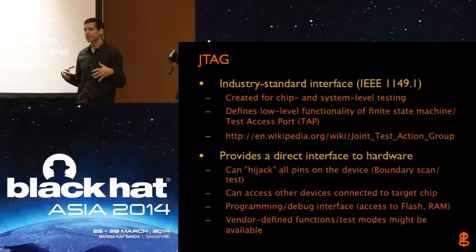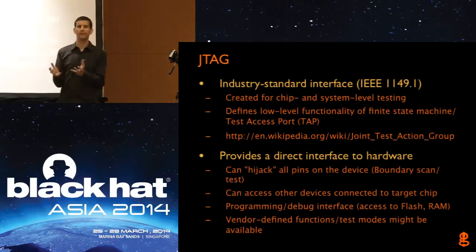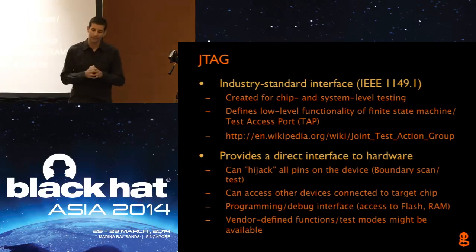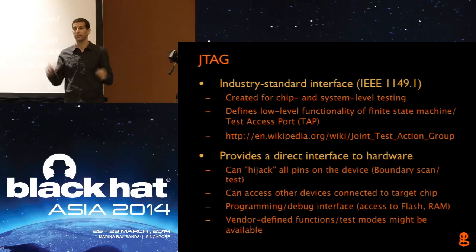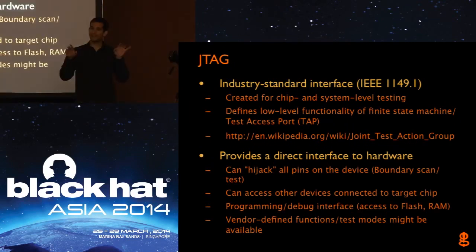Some vendors actually create additional vendor-specific functionality that can be communicated and controlled through JTAG. So it's become this universal interface when it really started as just a very low-level, specific interface to test the connections of pins on a circuit board. What's really cool about JTAG is you can actually hijack all of the pins on a device through something called a boundary scan, where you can individually control either outputs or inputs